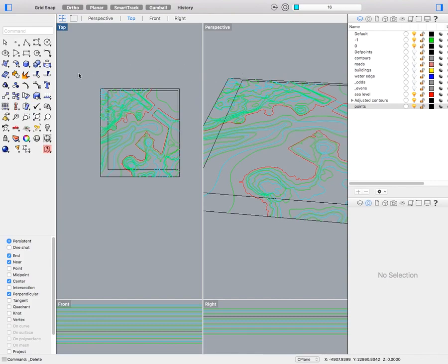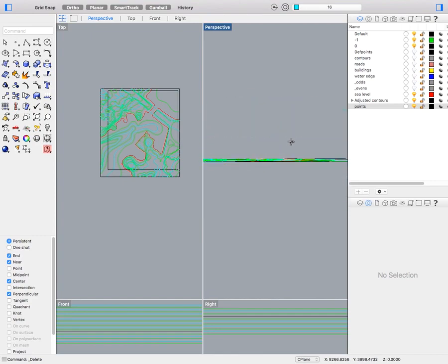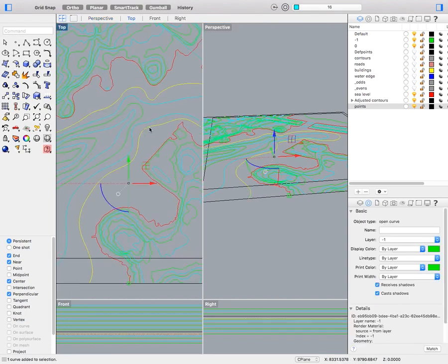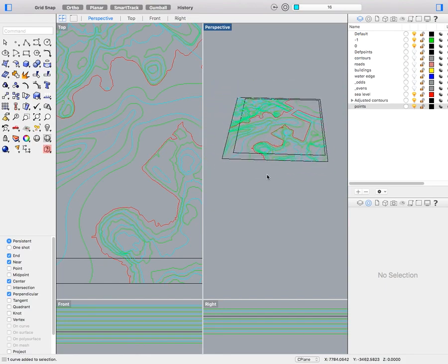So everyone needs to first obviously import their CAD drawing into Rhino. I've already taken Jeff's file from CAD. He's manipulated all of these lines and actually put them at their correct elevations in 3 dimensions, which is quite simple, just taking each of these lines and moving them up by whichever increment you have them. So if you do that first, and then once you have the file set up that way, it's quite easy